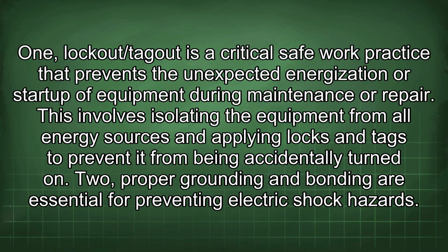1. Lockout/tagout is a critical safe work practice that prevents the unexpected energization or startup of equipment during maintenance or repair. This involves isolating the equipment from all energy sources and applying locks and tags to prevent it from being accidentally turned on. 2. Proper grounding and bonding are essential for preventing electric shock hazards.